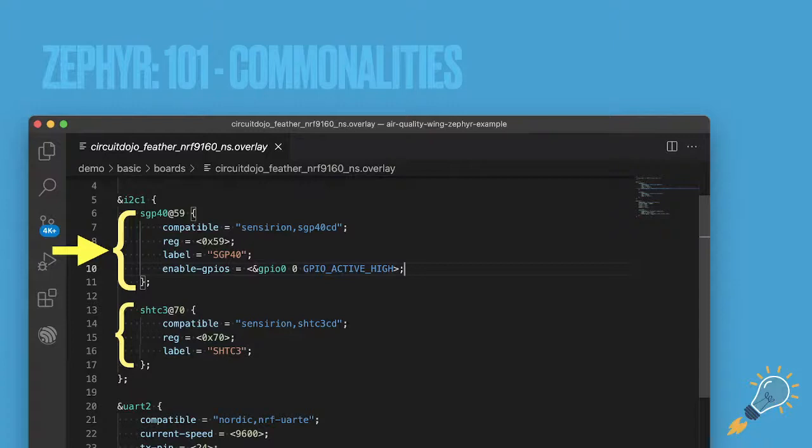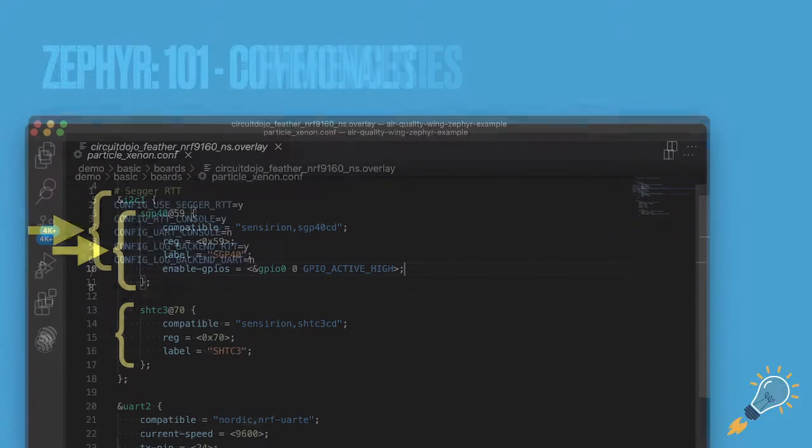Depending on what interface you're using, on one board you might be using I2C2, or you might be using UART1. This allows you to map these parts to the interfaces that you're actually using. And that's the power of Zephyr. This is the work you need to do on the back end to make sure things are working properly.